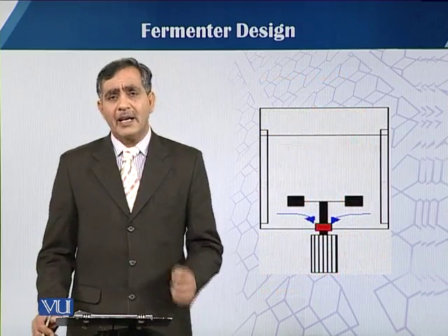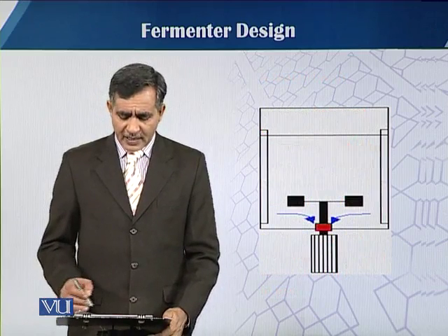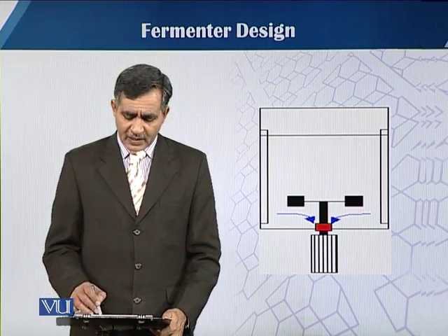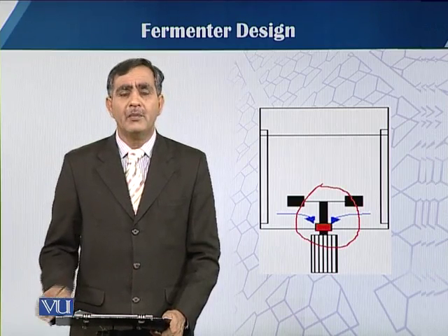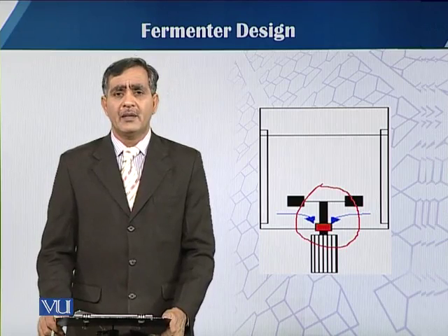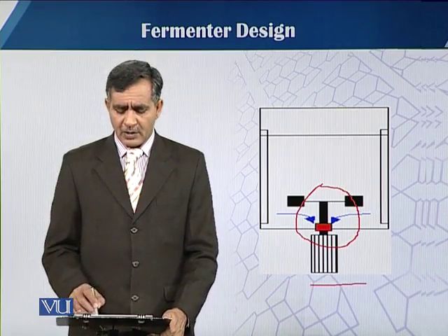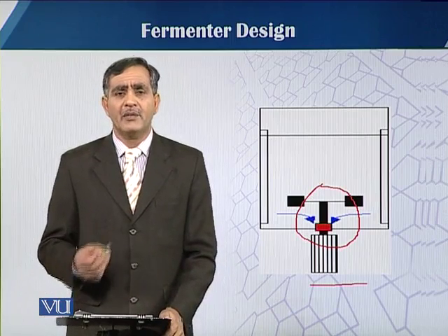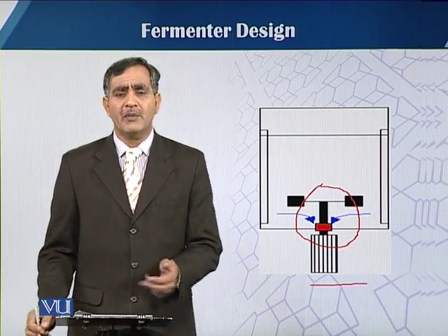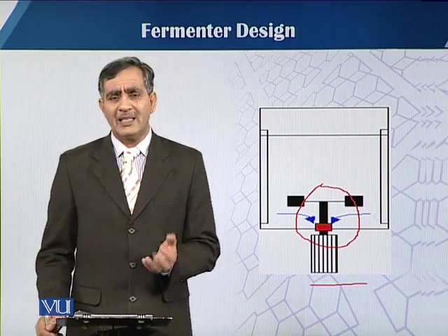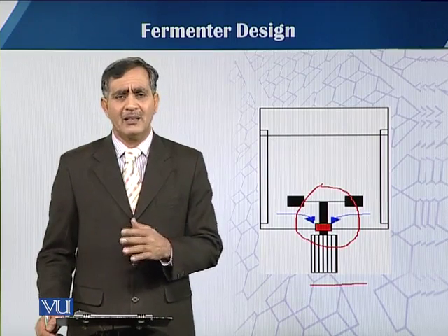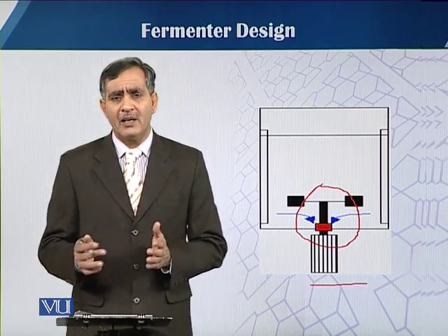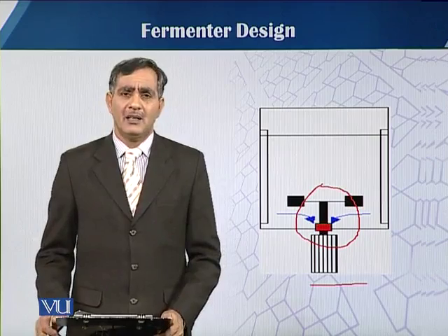In this diagram, we can easily observe how the shaft enters from the bottom of the fermenter, because the motor is placed on the bottom, so the shaft has to enter from the bottom. In this case, we have a problem when there is precipitation or crystals and some other salt present in the medium, which can affect the seal quality and cause disturbance.